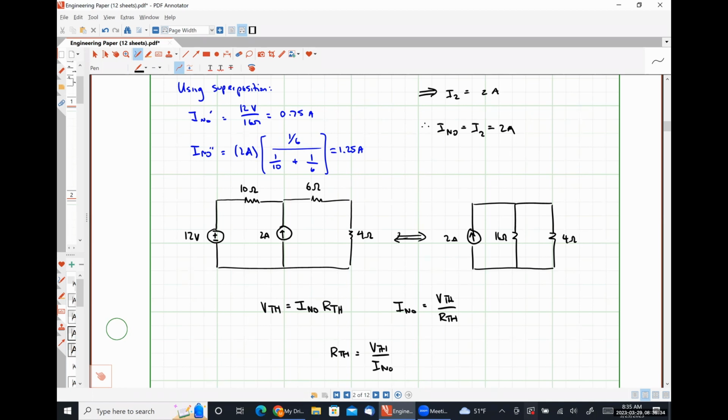So on your exams and things like that, because you guys are terrified of nodal analysis for whatever dumb reason, you could find the Norton equivalent current using mesh analysis or something like that, find the equivalent resistance, and then use those 2 pieces of information to find the Thevenin equivalent voltage without ever having to do nodal analysis or anything like that to find V Thevenin for a particularly difficult circuit. Okay.